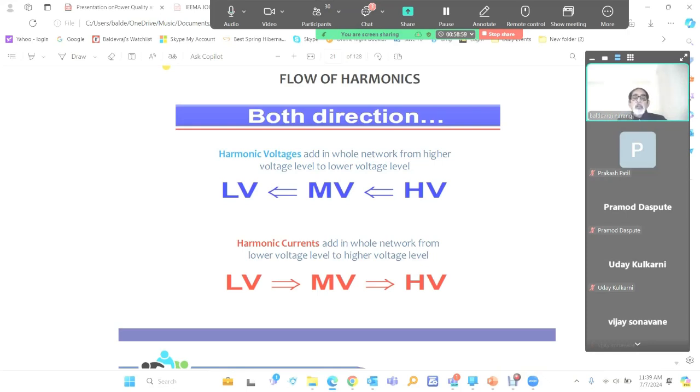And at each voltage level, they are getting converted to voltage distortion, which we call voltage harmonics. So at all these buses, voltage harmonics affect all the loads connected to that bus, whether they are linear or non-linear, everything is affected. And from the grid itself, whatever voltage distortion is there flows back towards the low voltage. So this is the flow. Current is from low to high, and voltage harmonics are from high voltage to low voltage side.